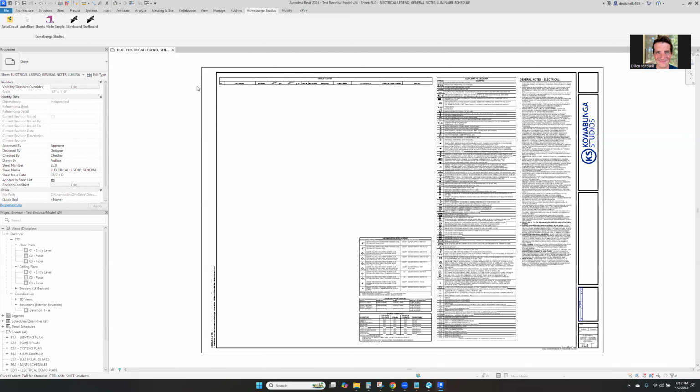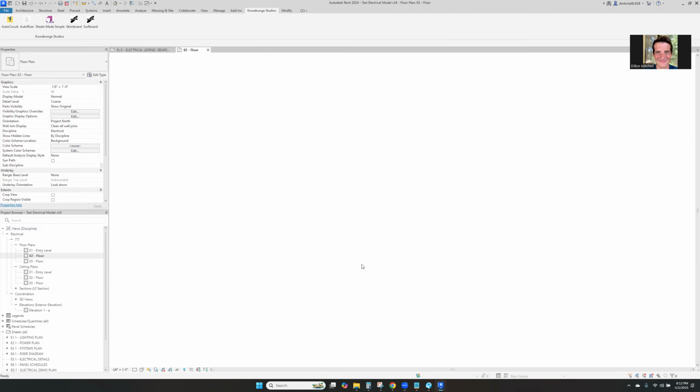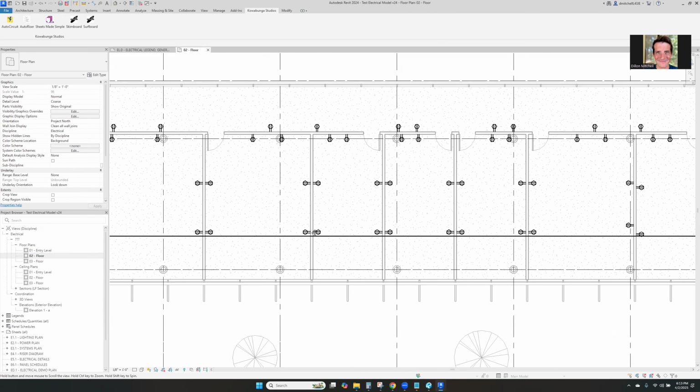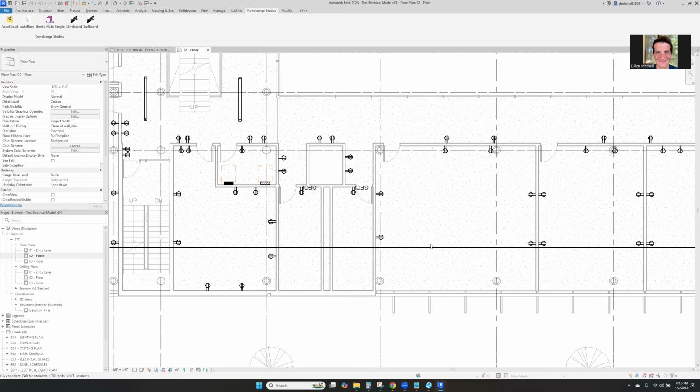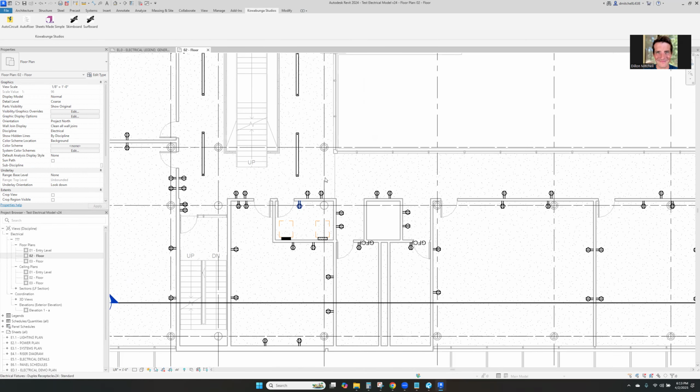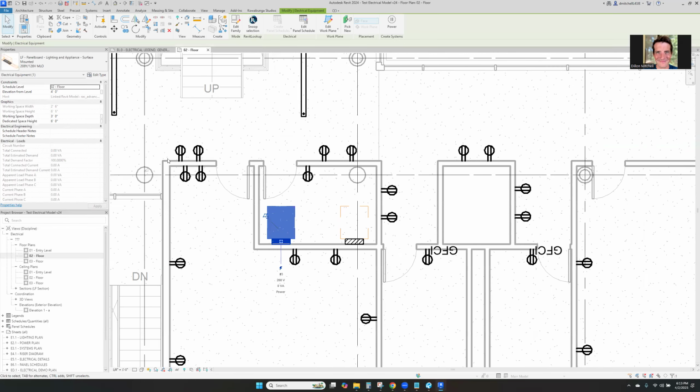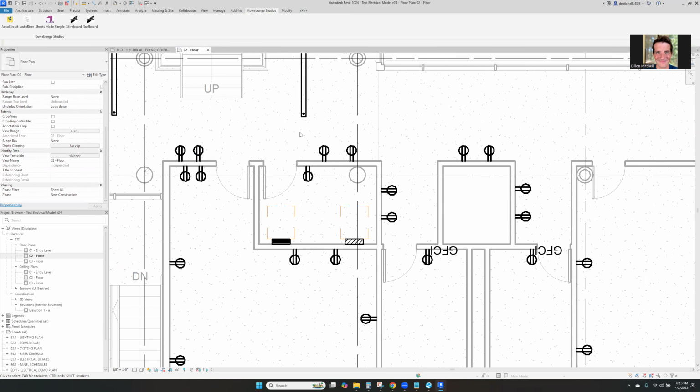In this video, we're going to walk through AutoCircuit. I already have set up in the project a whole bunch of receptacles throughout the model. We have low voltage panels or 208 panels that have a distribution system applied to them. They're named, numbered, all that kind of good stuff. We've got a panel name over here, so we are good to run AutoCircuit.